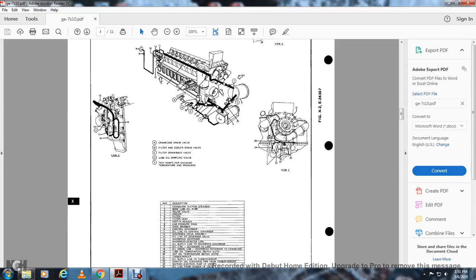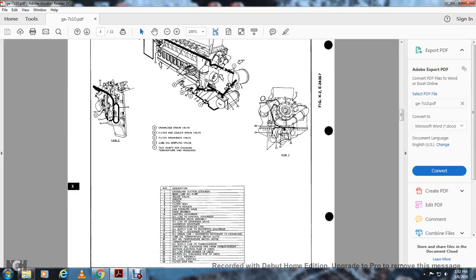13 oil line to the governor drive, 14 overspeed governor, 15 overspeed derate linkage, 16 oil supply line to the overspeed governor, 17 oil line governor to linkage, 18 oil drain line overspeed governor to the crankcase, 19 lube oil temperature switch at the end of the train, 20 hot oil temperature switch at the head end of the train, 21 turbocharger, 22 oil supply line to the turbocharger, 23 oil discharge pipe from the turbocharger section, 24 suction for ejector pump if used, 25 oil from the header if used, 26 suction oil discharge pipe if used, 27 oil fill assembly, 28 oil level dipstick, 29 fill drip